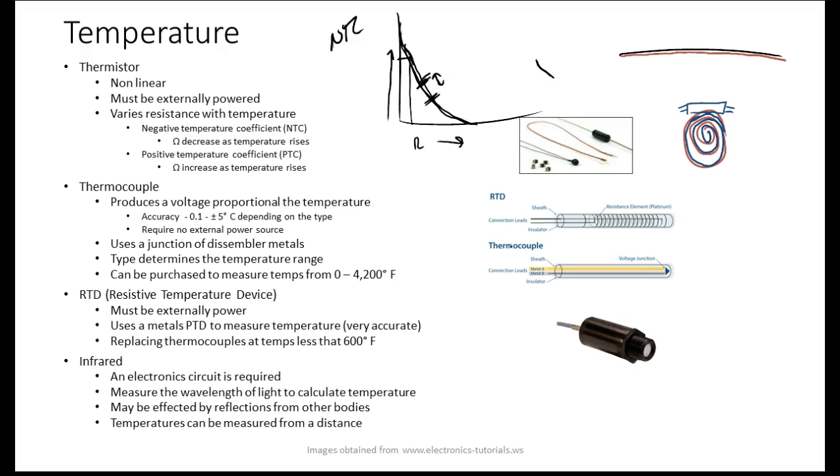To cool off. Well, we can use these in thermal switches all over the place. And they're pretty accurate too, so they'll trip at a certain temperature. But when it cools down, it will do what? It'll automatically do what? Reset. So we use these in small horsepower motors as the overloads, where they'll put it in series with the stator on the motor.